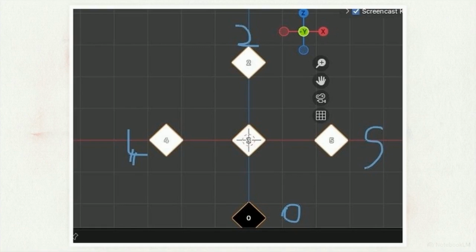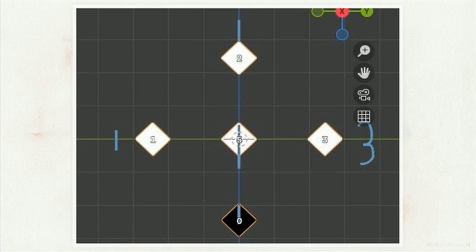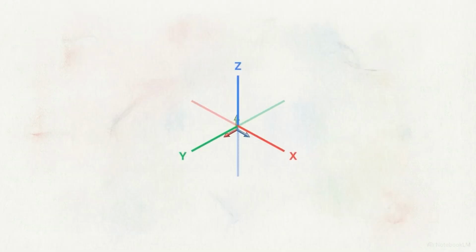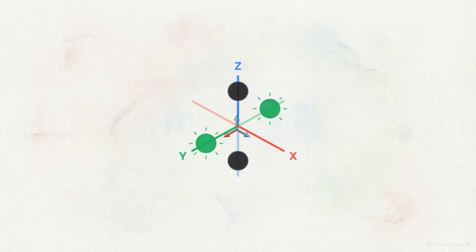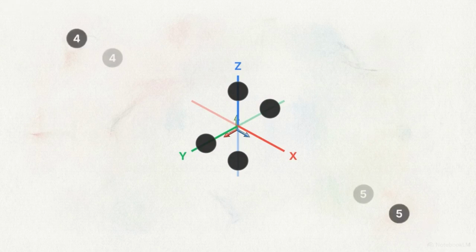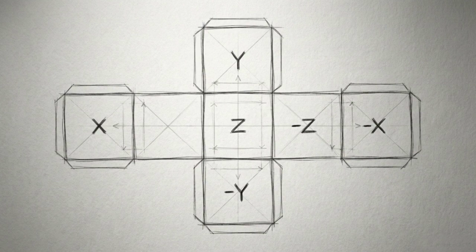These numbers tell us which faces are currently pointing towards the camera. Switching to side view reveals indices 1 and 3. By isolating these specific IDs, we can write rules that only apply color to the faces pointing in a specific direction. The data shows that indices 0 and 2 align with the z-axis, 1 and 3 with the y-axis, and 4 and 5 with the x-axis. This gives us a logic-based map for the materials.